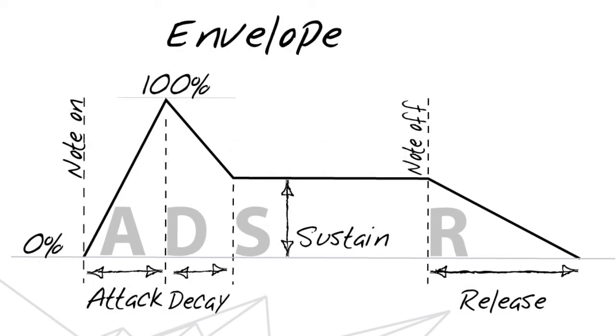An envelope is a set path of time and value levels that are applied, and they help in shaping signals. Using ADSR, we can shape how a note event will happen. When we hear a note on a piano or a guitar, we hear a note initially goes up to some value and then eventually falls to nothing. And this follows a pattern that is characteristic of a particular instrument. So the volume pattern of any note played on any instrument is known as volume envelope.